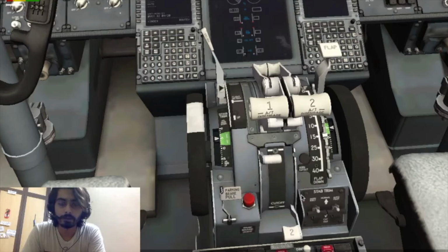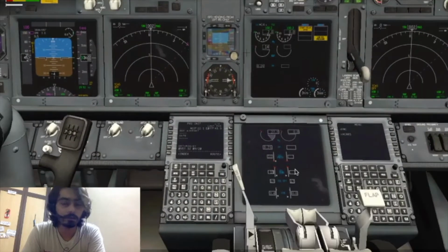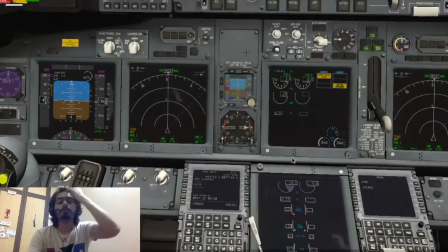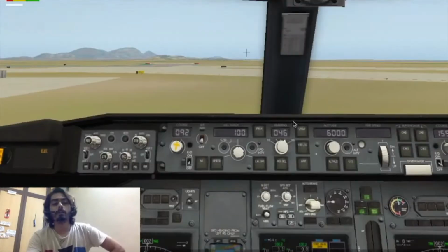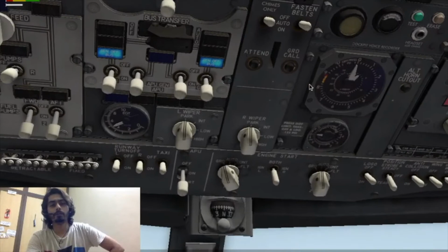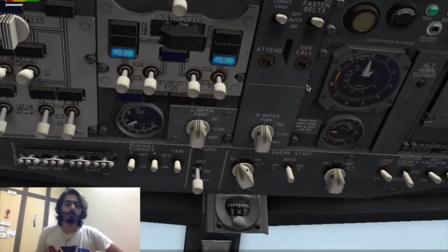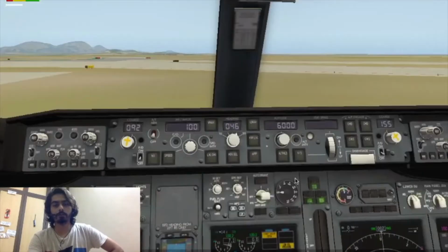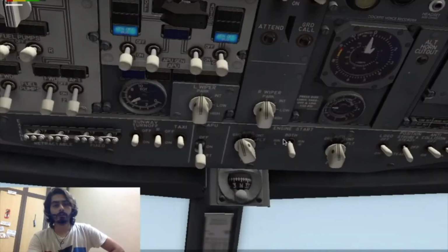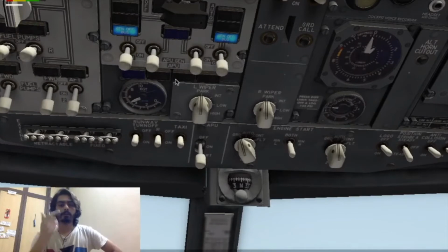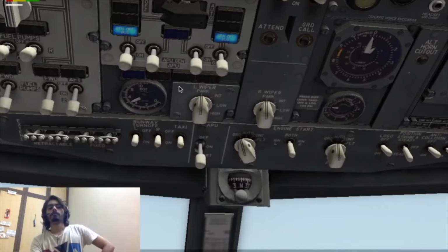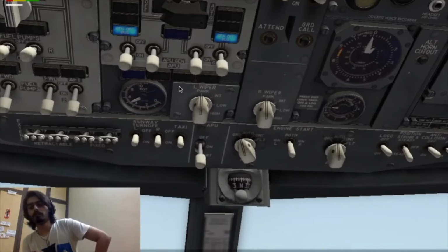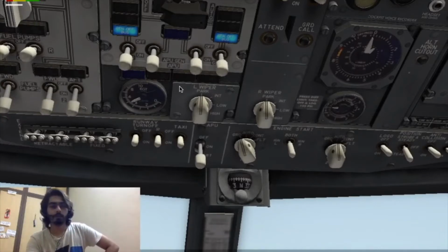I'll set this to idle, and now our first engine, the left engine, will go to good power, and we'll wait for it. By the way, so far our aircraft instruments are running on APU power, right? The auxiliary power unit that we explained at the tail. What we now need to do is we need to eventually turn the APU off. Why? Because we'll discuss.